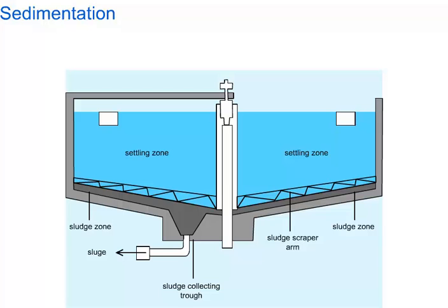Sedimentation basins may be rectangular, where water flows from end to end, or circular, where flow is from the center outward. Sedimentation basin outflow is typically over a weir, so only a thin top layer, that furthest from the sediment, exits. The amount of floc that settles out of the water is dependent on basin retention time and on basin depth. The retention time of the water must therefore be balanced against the cost of a larger basin. The minimum clarifier retention time is normally 4 hours.